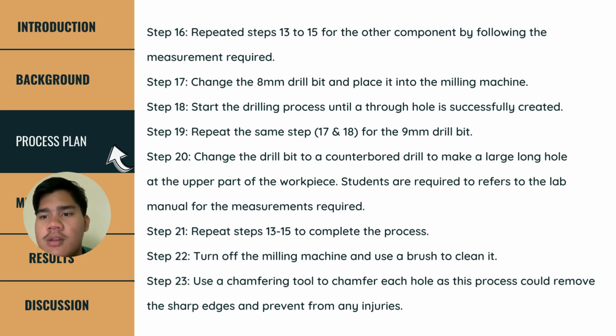Change the drill bit to a counterbore drill to make a large long hole at the upper part of the workpiece. Students are required to refer to the lab manual for the measurement required. Repeat steps 13 to 15 to complete the process.